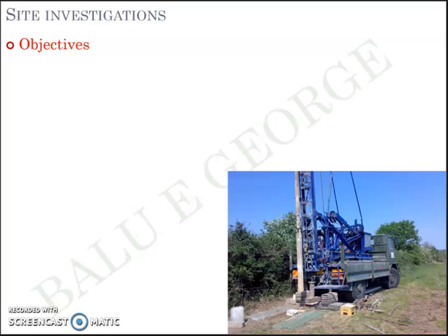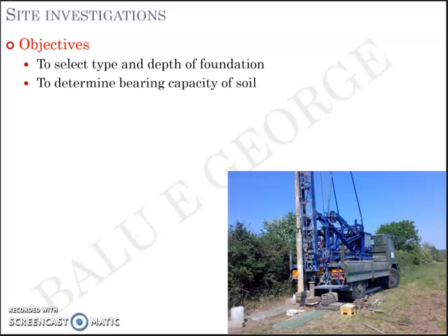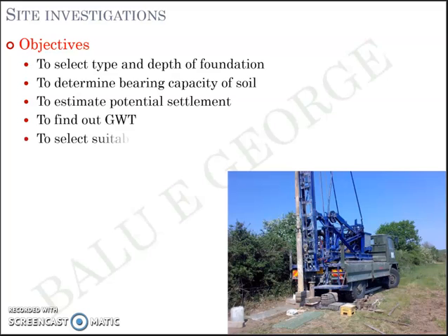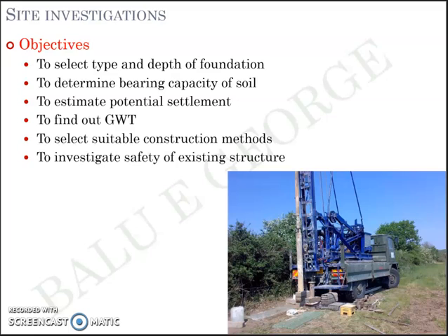A few objectives of site investigation are listed here: to select the type and the depth of foundation, to determine the bearing capacity of the soil, to estimate the potential settlement, to observe and find the groundwater table, to select the suitable construction method, to investigate the safety of existing structures, etc. Though it's not limited to this, it includes all the points that I've listed here.